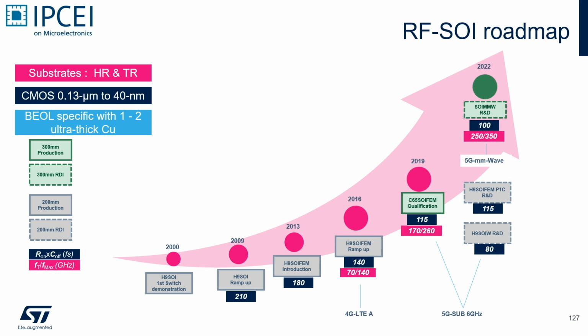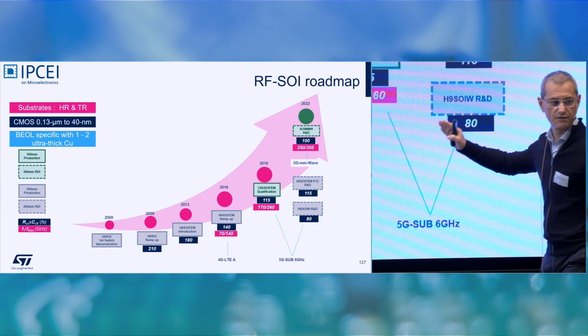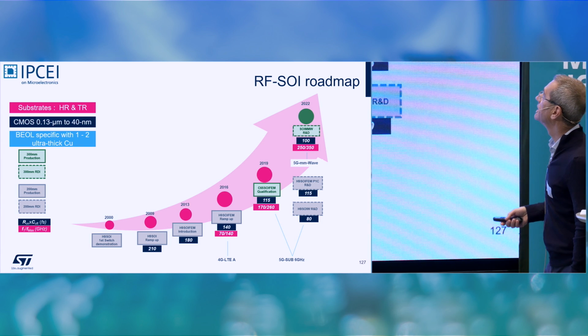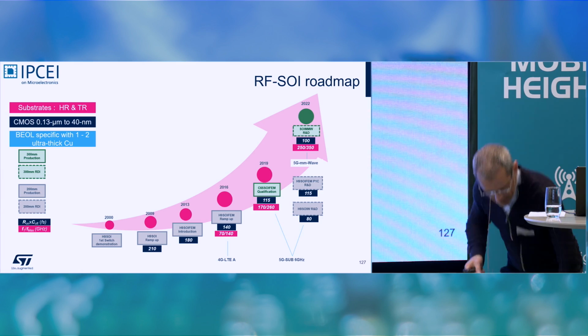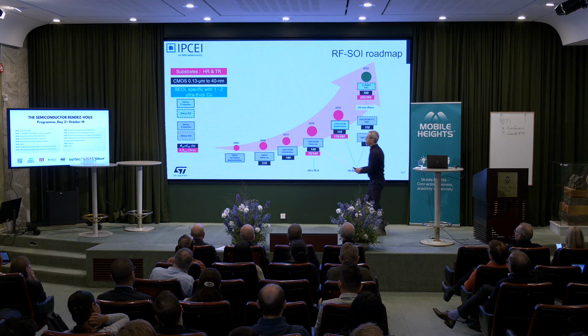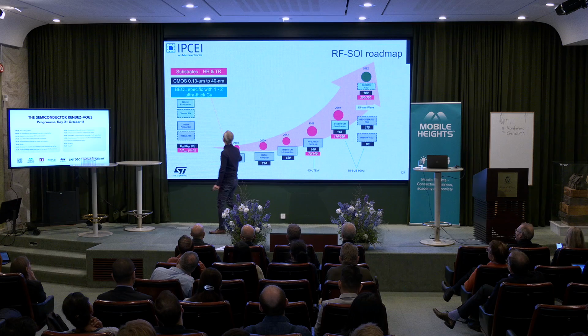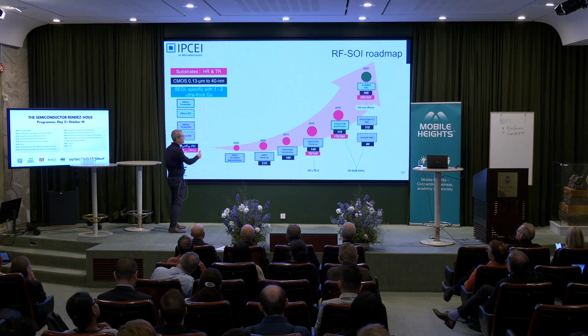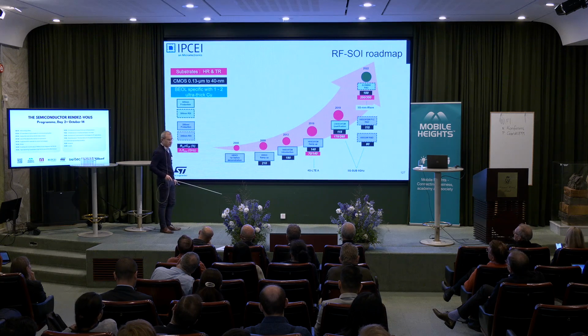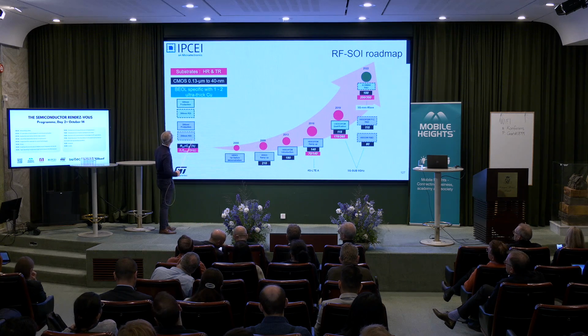For SOI wafers, this is a kind of roadmap looking back to the 2000s here. I will not explain all this history, but it's just to tell you that ST has a long history with RF SOI CMOS. We are using high resistivity and trap-rich wafers from Soitec, as was described by François yesterday.